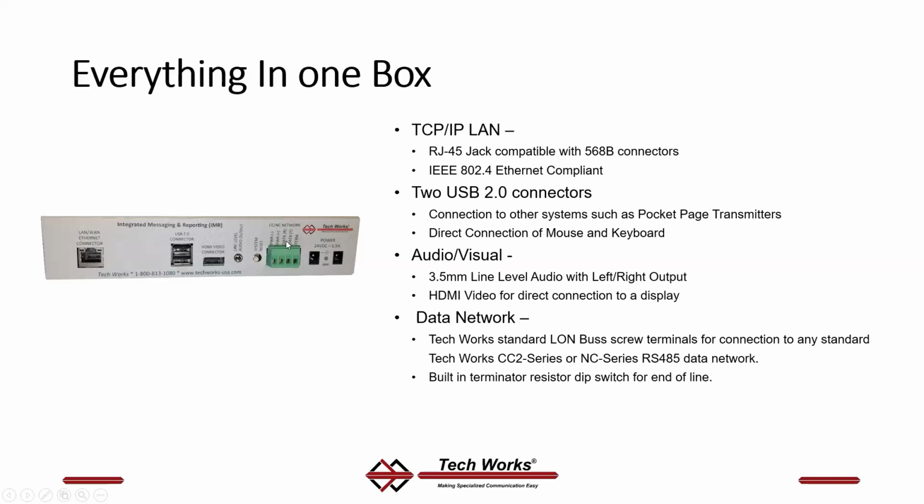This is your RS-485 data transmit and receive, as well as your network power plus and minus. Over here to the right, you can't quite see it, but there's a switch that gives you a built-in terminating resistor if this happens to be the last item on the end of this RS-485 network.